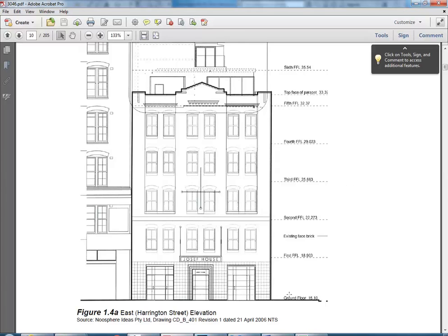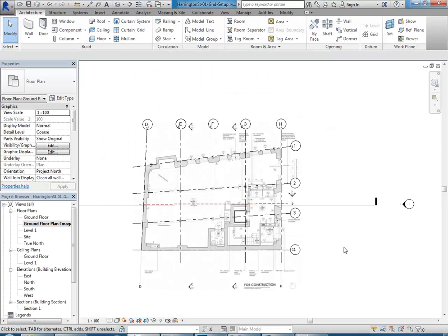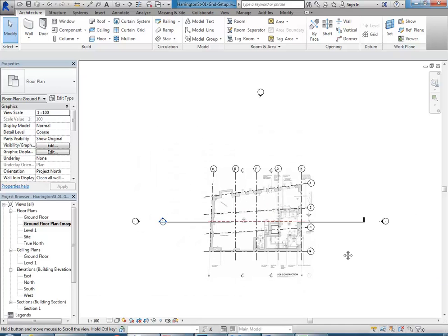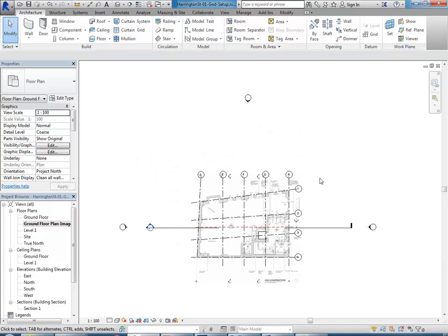So here you can see we've got the ground floor at 15.1. So that's AHD from sea level, essentially. And again, you need to make a decision how you're going to set your projects out. You can just work with those levels, and I think maybe with this, because it's not really that high, we can do that. But if you've got a level like 40 metres or something like that, then it's a long way to lift everything up, because again, Revit wants you to physically move everything to that location if you want that number to appear.